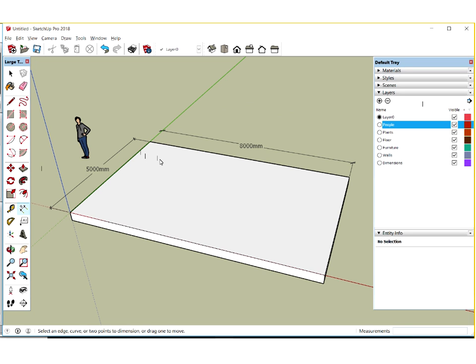It's always good at the start of a project, especially if I draw a house slab or something like that, to pin dimensions on it as a checkpoint, to make sure that I haven't accidentally clicked or made a quick little typo in the wrong spot. Then all my walls depend on that and other things. So it's a good first thing to do on a project, just to check your basic dimensions so you're not building geometry on top of something that's slightly the wrong size, which is very easy to do, trust me.